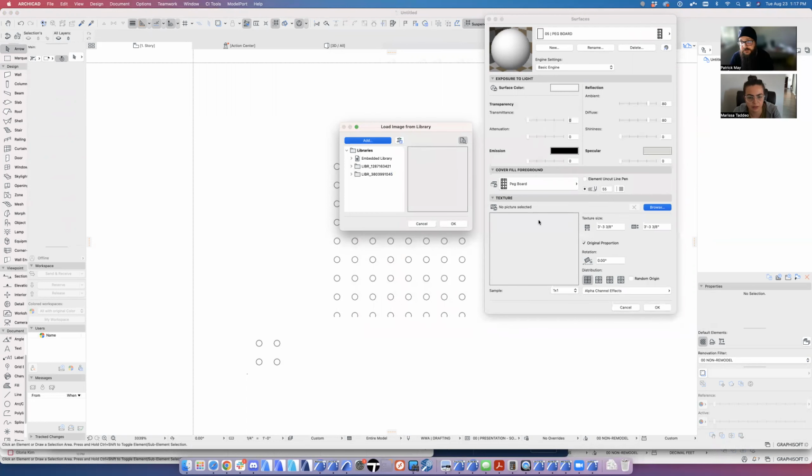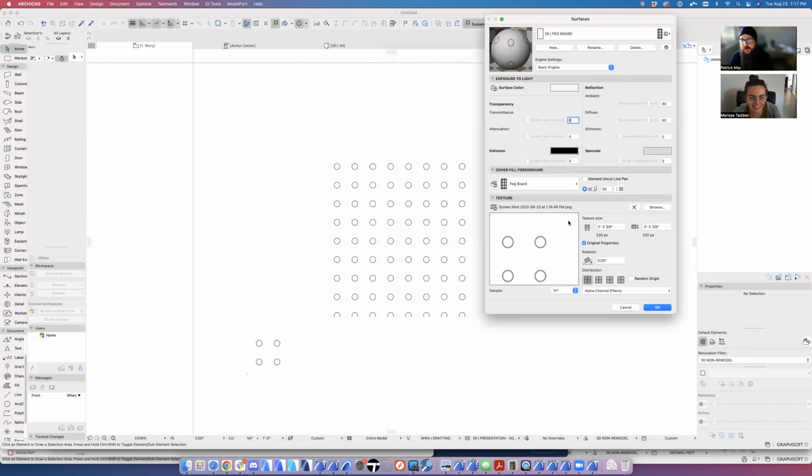Obviously not named screenshot, but for now, the purpose is what we're working on. You do need to make sure that the size of this thing is proportionally what it needs to show on the elevation. So whatever that was, what were we at? We were 1.5 plus 3/8, so we were 2.25 inches or something. So you just set that to match whatever that surface was, and then say okay.